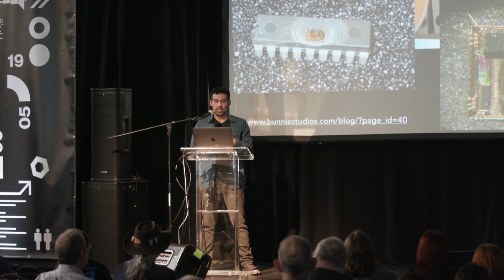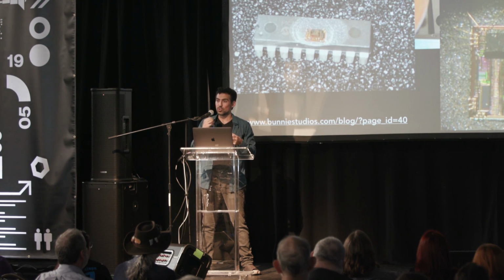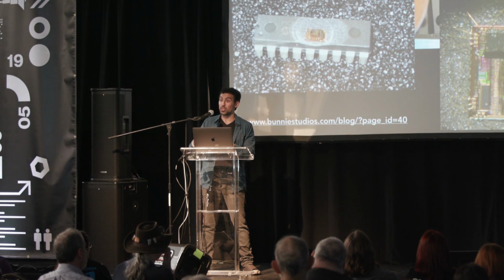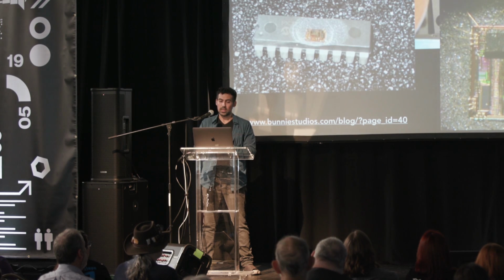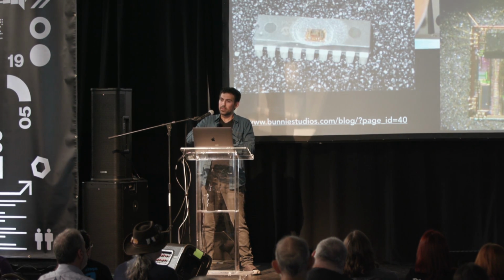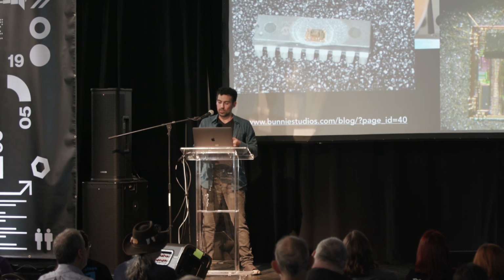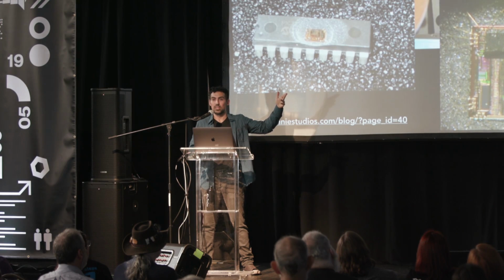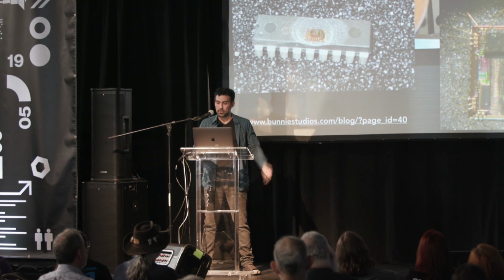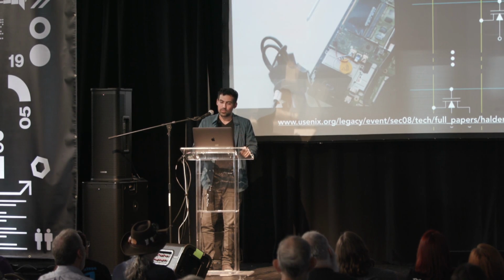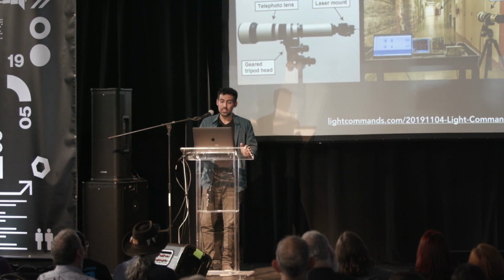So what Bunny did was he had a chip. It had firmware that he wanted to extract, but there was a fuse set that said, no, I'm not going to allow any debugger or external device to extract any firmware. So he opened up the chip, he drilled inside of it, he covered part with electrical tape, and then shone UV light on the rest to reset the fuses, because it's UV light that resets them, and was then able to connect and extract information. So ultraviolet light, temperature, visible light.